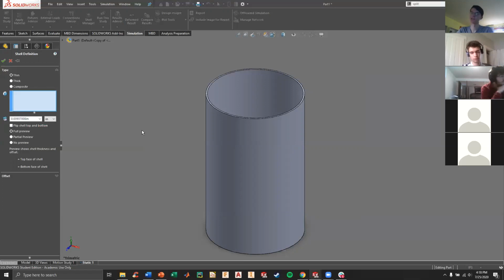Generally where that's applicable, let's say you're doing a kind of scaffold structure, you don't need to know the exact 3D forces at every point in a 20-foot long aluminum or steel pole in 3D space. Really, you can just model it as a single beam, and the general forces will make sense. And when you do it, you can set some parameters like the thickness of it and all that kind of stuff. And that'll speed up the solve of your model considerably, many, many times.